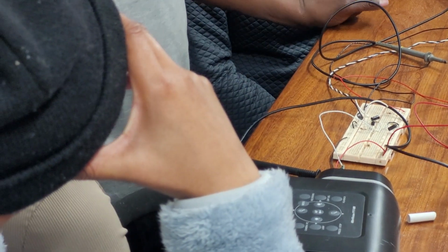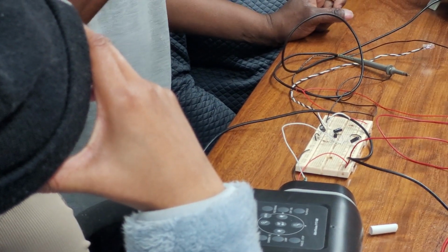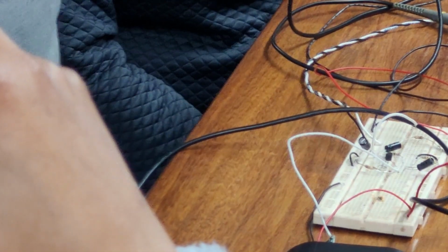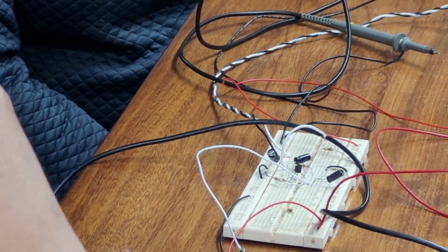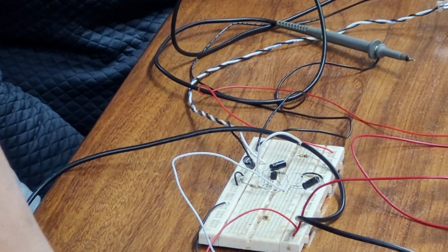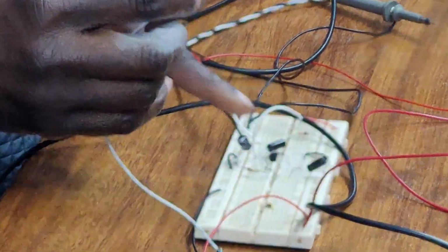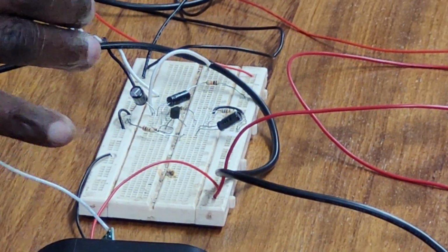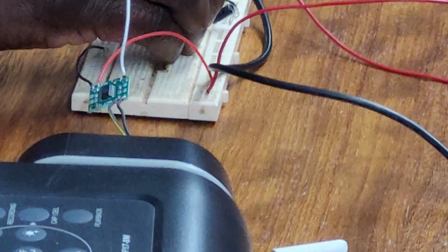That's all. So what I decided to do was to bring in my class D power amplifier that can deliver up to 10 watts of power. Believe it. Switch mode power amplifier, which is going to take this tiny input and do something with it and drive hopefully a speaker. So I'm taking the output of that circuit from that capacitor, between the capacitor and the 1K, as you can see, connecting it to this class D. This is external, okay?